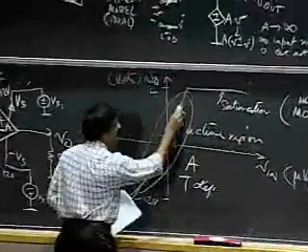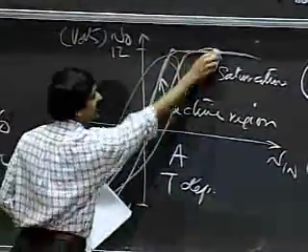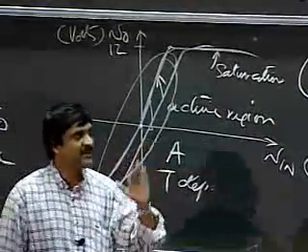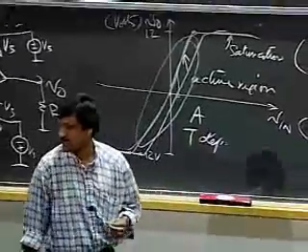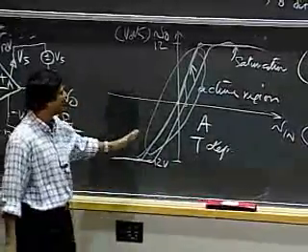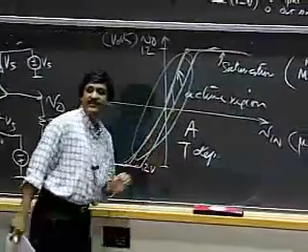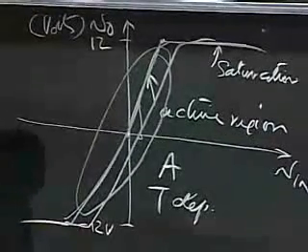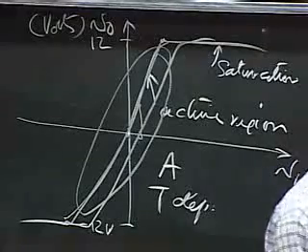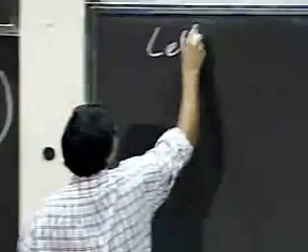So what you saw there was that the op-amp began to behave really weirdly as I heated it. Instead of doing this, it sometimes did this. It did really weirdly, getting an offset from the center and so on. It does a bunch of other weird things, but we won't go into those details. It's not relevant for this course. But the point is that the gain and the offset at the input are dependent on temperature, and we'll look for ways to make it less dependent on temperature. So as a next step, what I'd like to do is build a circuit.